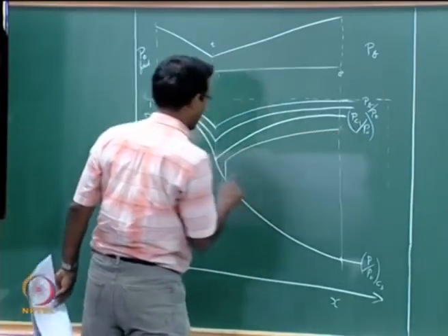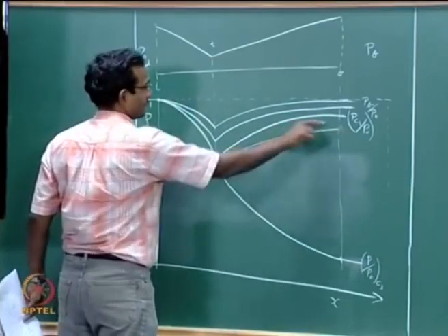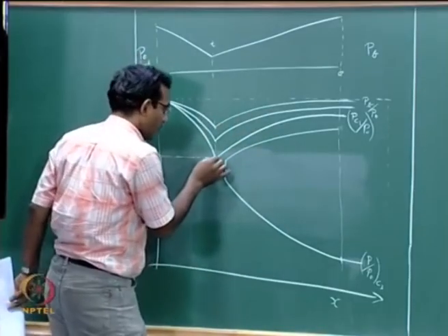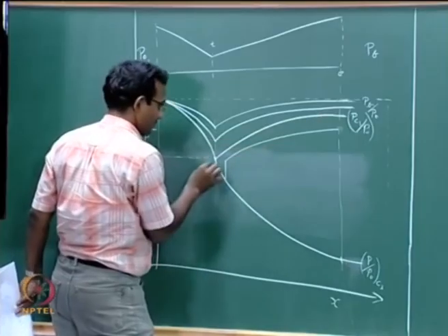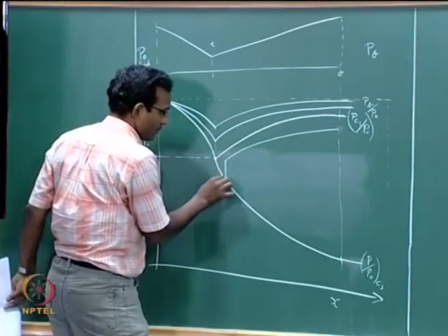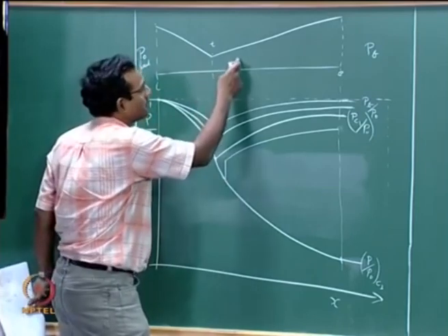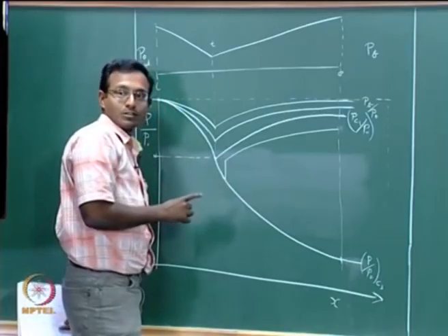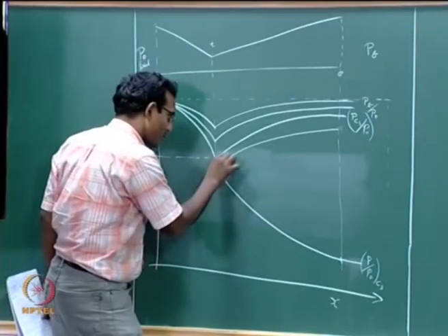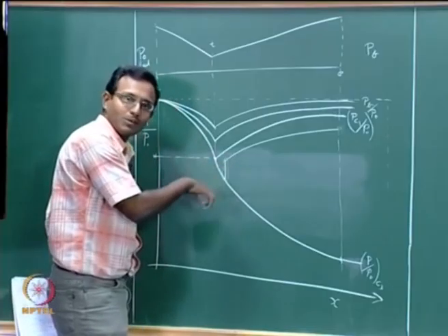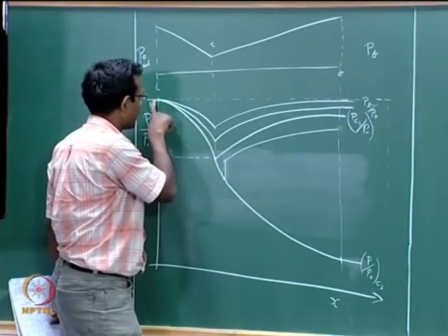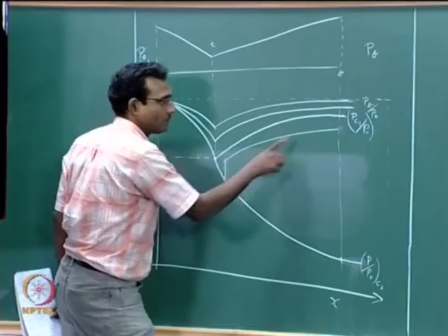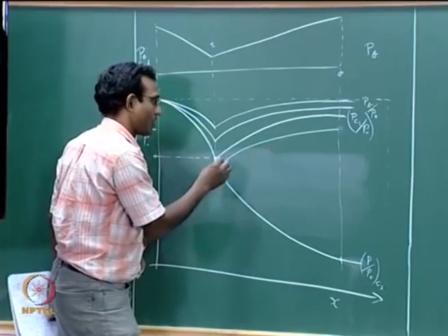We already know that if it is subsonic flow in a diverging duct, it is going to increase in pressure, similar to these curves. We already have subsonic solutions. Now this is what the flow does. Once it is below critical pressure 1, it is going to take the supersonic path for some distance, and then it is going to jump across to the subsonic solution using a shock, non-isentropic flow again. Only this one spot is non-isentropic really, just that one region. Everywhere else it is isentropic. From here to here it is P01, and after this it is P02 really, because there is a drop in P0 across this shock.